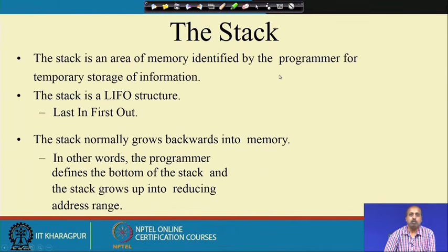Next, we will be looking into another very important aspect of any processor based program execution, that is called the stack. If you think in terms of the architecture or organization of the system, the stack is an area of memory identified by the programmer for temporary storage of information.